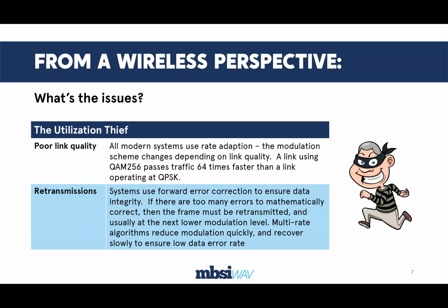many manufactured systems will send the transmission at the original rate. Let's say it's QAM 256, but there's a fade going on, and I no longer have the 28 or 30 or 32 dB of signal to noise ratio that it takes to support that QAM 256. So let's say it drops down to 25 or something like that. Well, now I'm firmly in QAM 64 territory. So lots of systems will retransmit at the same rate once, and then retransmit the second time at a lower rate.